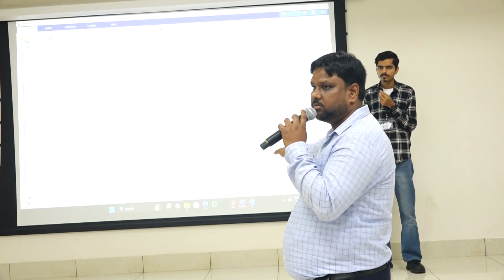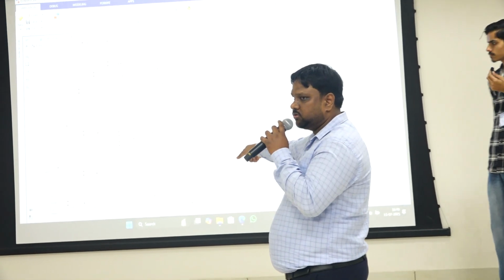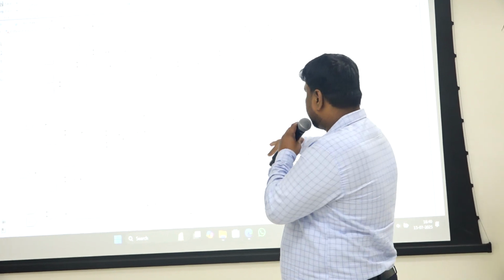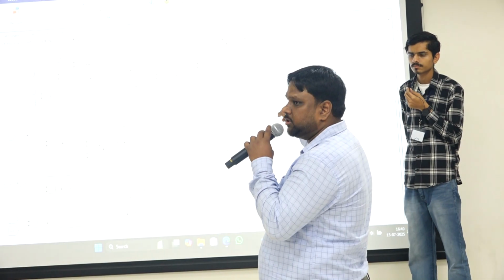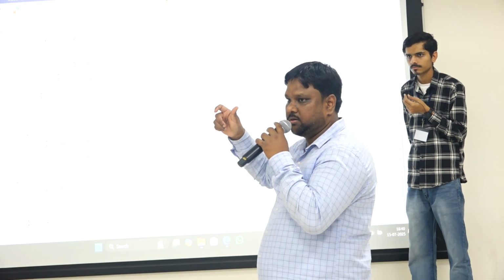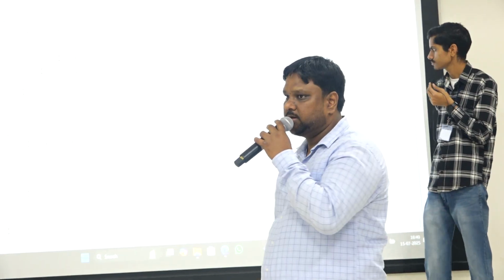Understood? So if you see, it is a controlled voltage source, and that control signal is the summation. Can you show which one? U cell, right? That is the summation of two potentials, and after these two potentials you are left with ohmic. So these two potentials plus ohmic is equal to V cell. Get it?